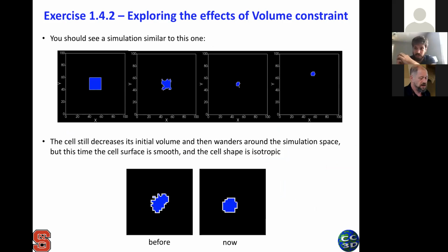and happens super fast. If you could not see it, stop the simulation, and instead of hitting the play button, hit the button next to it, the one with the circle inside, and then you can play the simulation step by step, and you can see those intermediate states. Okay.